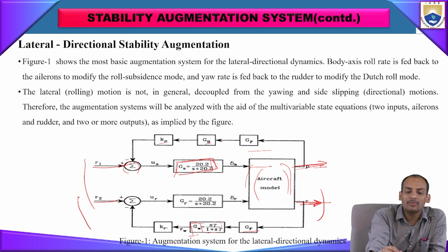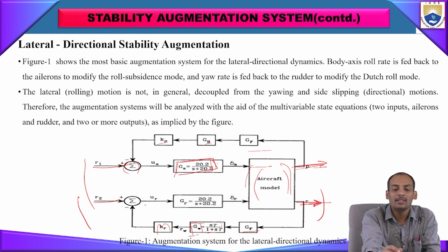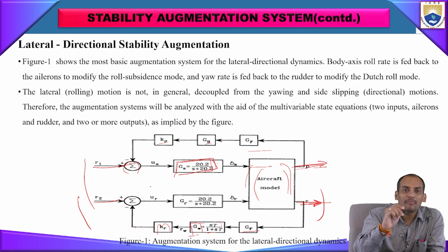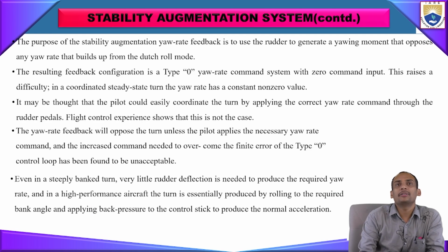The roll rate we have also given as feedback to the summing amplifier, so that by taking the feedback from here, that signal will be compensated, and whatever input is required for this transfer function will be automatically adjusted and given to this transfer function. Okay.